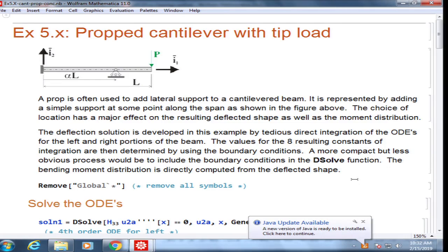Okay. And why is that? Because we are already defining displacement 0. Displacement 0 causes shear force to take a particular value, and that's the reaction force, right? So when you have a cause in the problem, you cannot have the effect on the same boundary. If you are imposing conditions on displacement, you cannot have conditions on shear force.